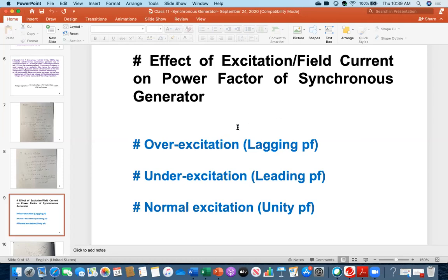Consequently, the generator needs huge excitation, overexcitation, to produce a high amount of internal voltage, because there is a drop, but the customer wants a certain voltage. As customers, your demand and my demand is that I want constant voltage, more or less, whatever the situation is.